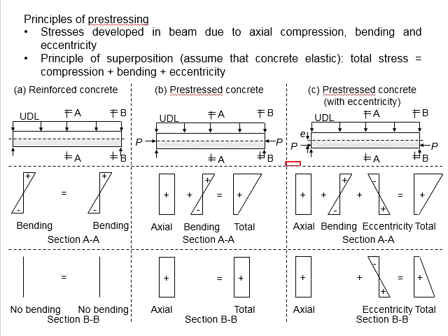The summations of all the stresses will be equal to the final stress acting on the member. Normally, you will need to check for the top of the beam and bottom of the beam, as these two normally represent the most critical situations in the beam section.